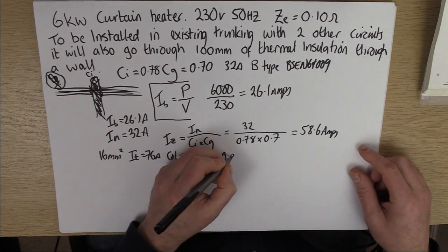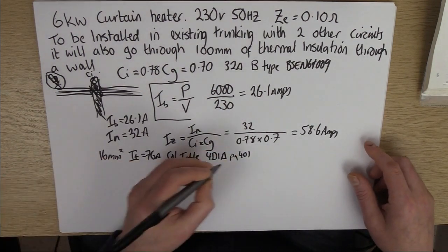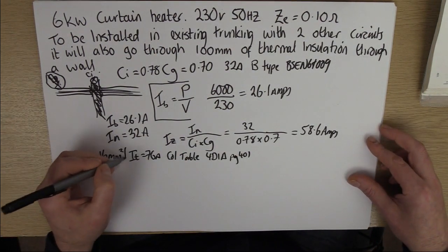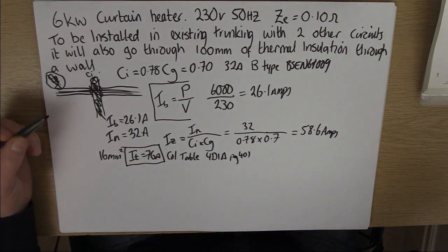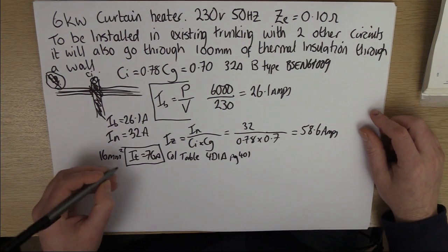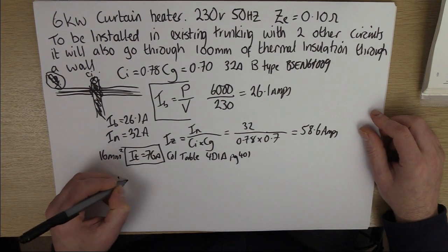Okay, put a page number, but that'll just be for you really. Okay, so now that's what we got. No chance of any overload, so you don't have to worry about that. That's good. And now we just need to check it for volt drop.